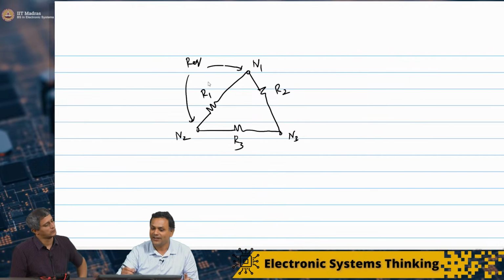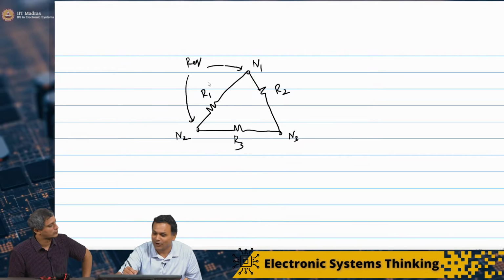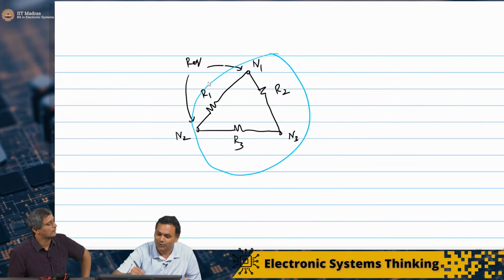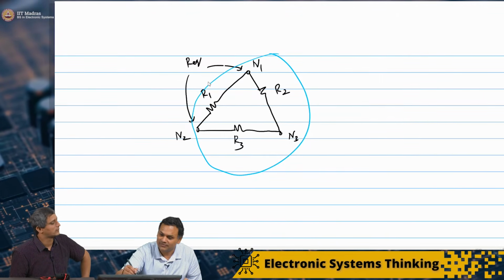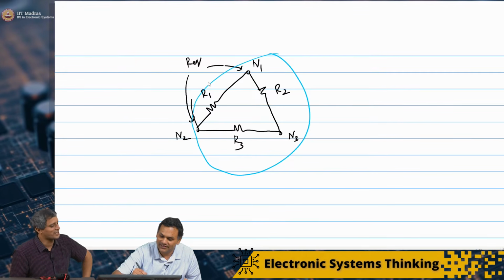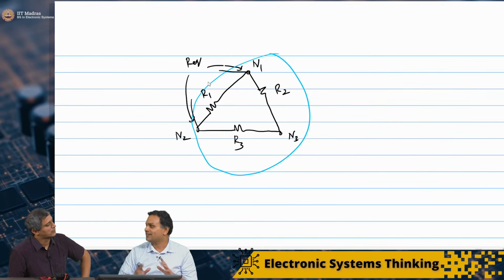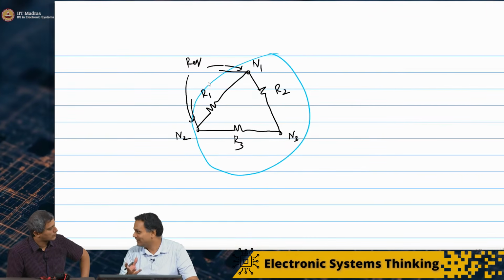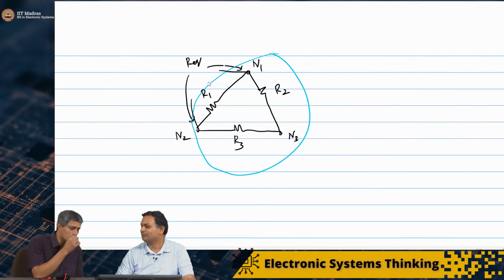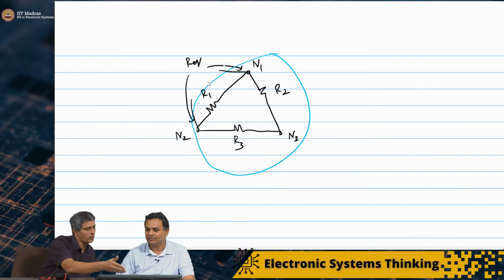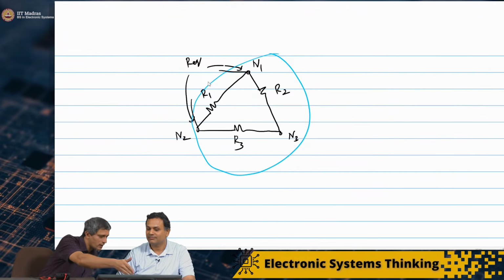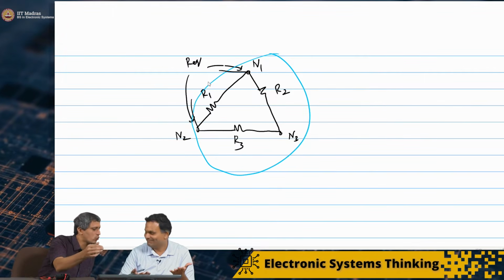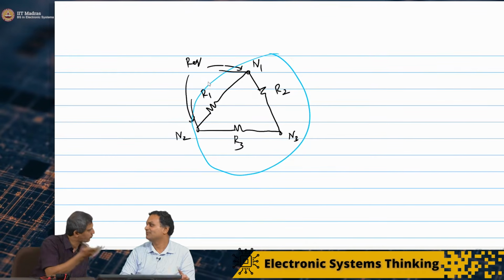I could have redrawn it, see, it is all happening inside the black box. All I'm doing is pulling out 2 nodes, 2 wires. And this is interesting. So students need to be able to imagine, maybe redraw in their minds. The foolproof way of doing this is: the current entering R2 has nowhere to go but to go through R3, and therefore they have to be in series.